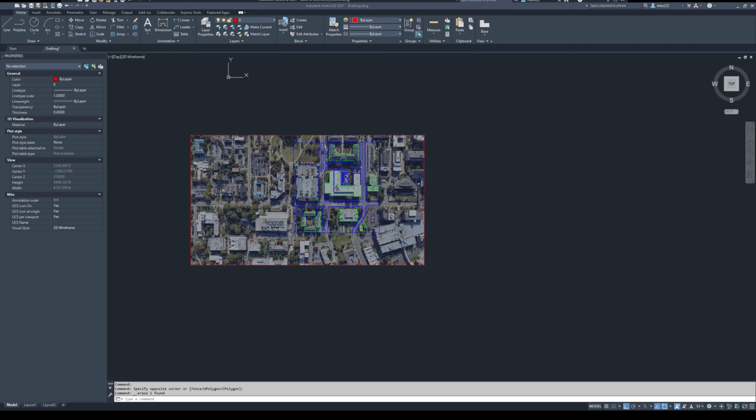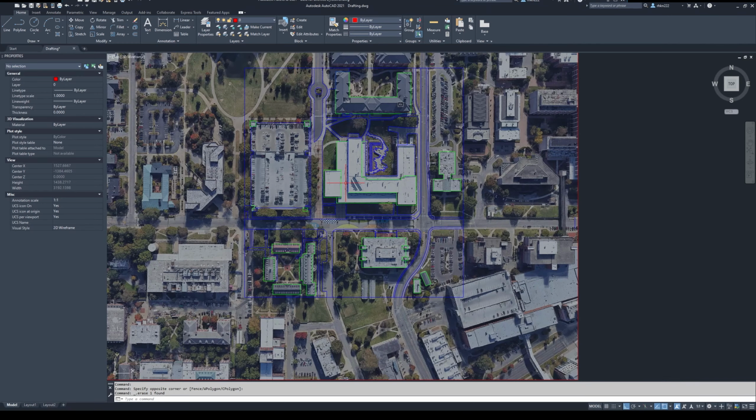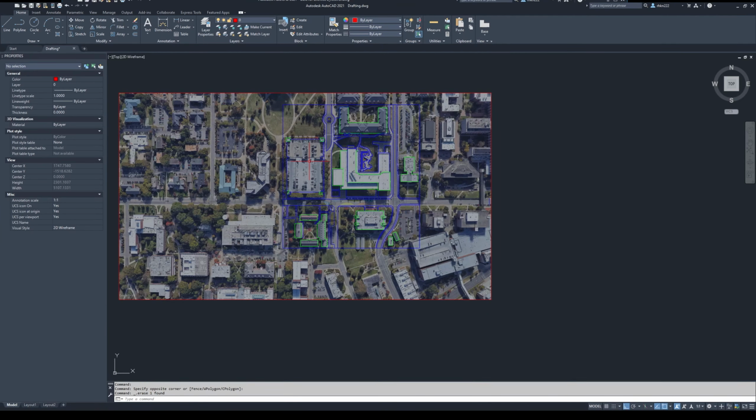So to start out with any project in 3D, what you want to do is probably start in AutoCAD. By this point in the program, you should know a little bit about AutoCAD, but the most important thing to know from CAD to SketchUp is to draw in as few layers as you can. For SketchUp, it's more helpful to have fewer layers, as there are less likely to be things you don't need. And when you're drafting your plan in AutoCAD, just make sure that you're drafting very accurately, that you're not having more line work than you need, and everything is drawn out to the right dimensions. And you can do that by overlaying aerials or using existing plans if you have them.